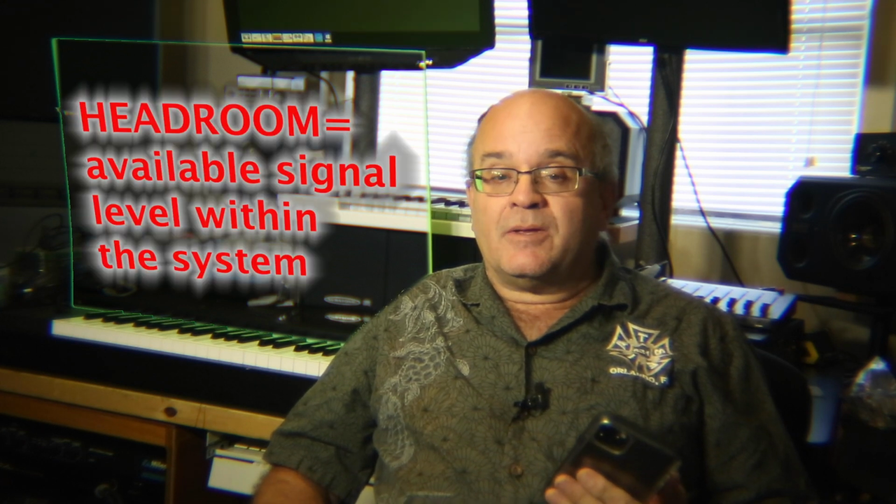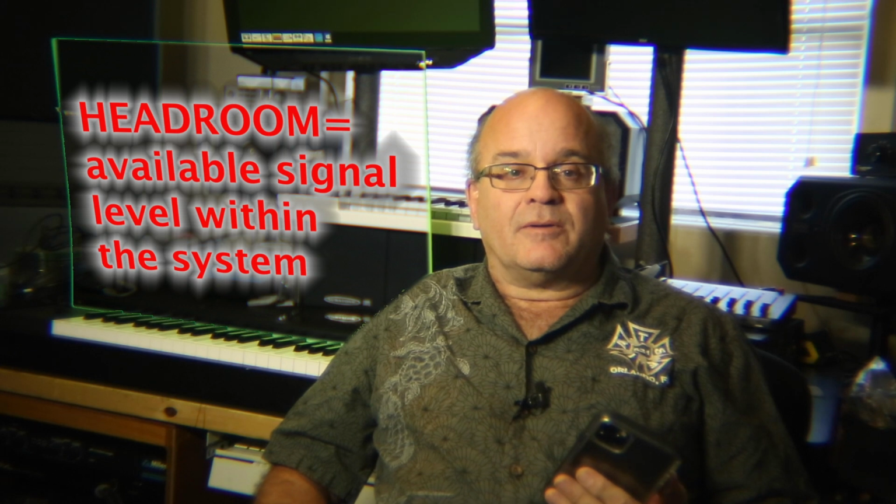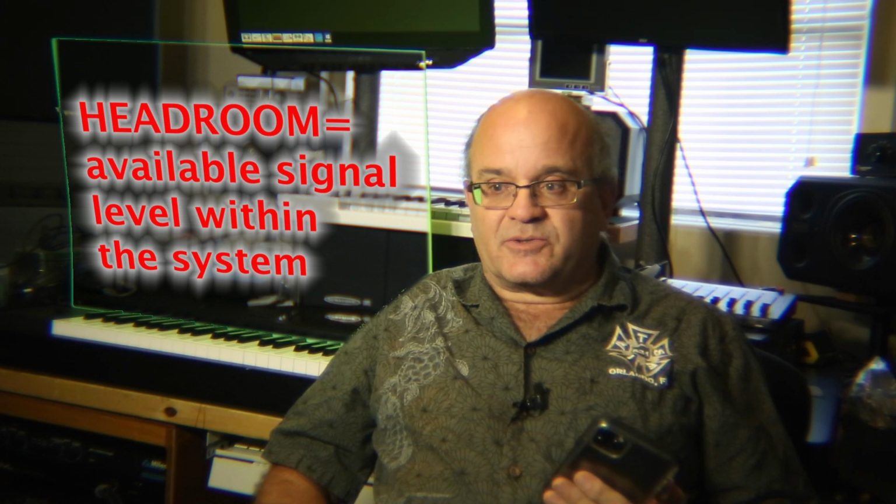So to make the math work out within the mixer, even though we're dealing with an analog environment, it's safer to start about minus 10 on everything. That way you have what's referred to as headroom, and you're less likely to peak out or overload the master bus of the mixer. These concepts, when taken together, are what is referred to as gain staging, or gain structure.